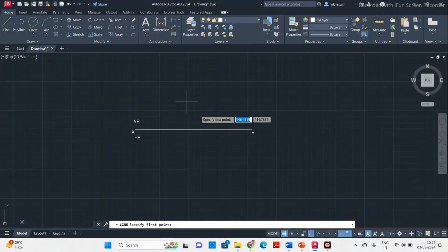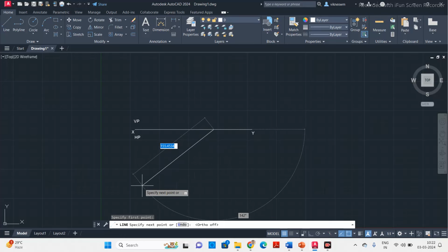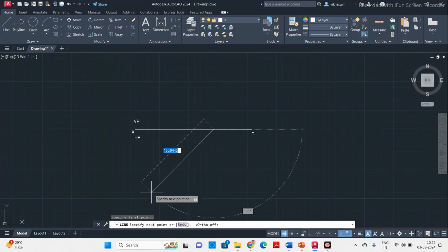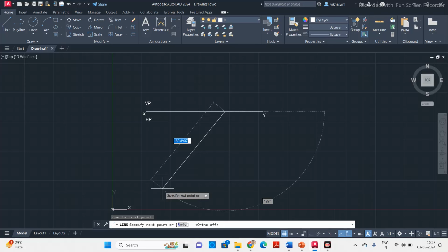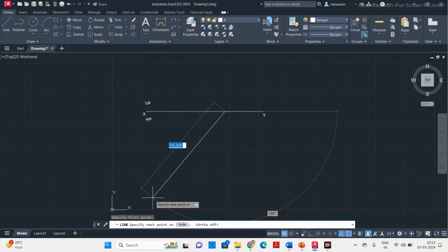Okay, take a line. So switch off this F8 so that you can get an inclination line. So put an inclined line for 30 degree. The length of this line you can take randomly. So I'm taking it approximately by moving the mouse cursor, and then I'm going to define the angle. So the other side of this angle should be this 30 degree.